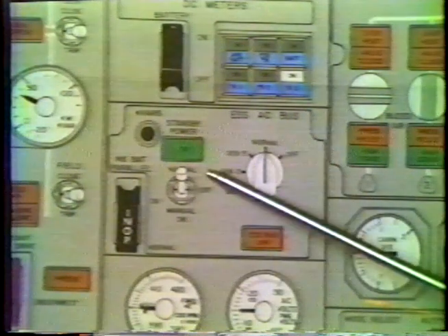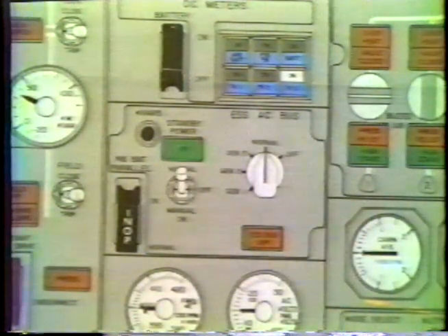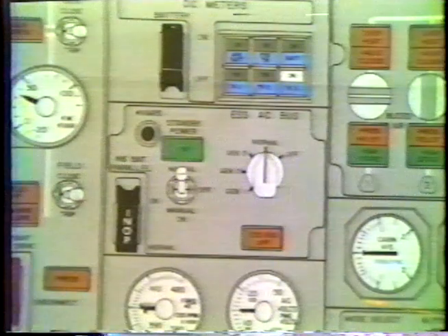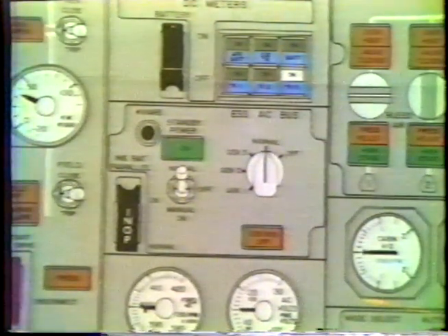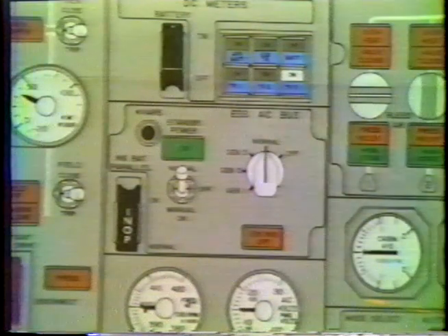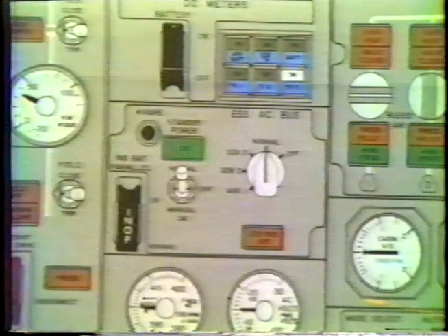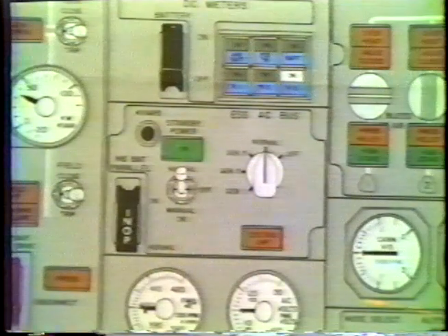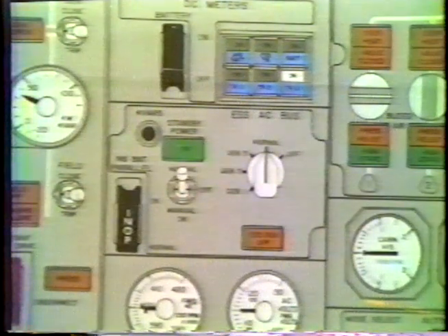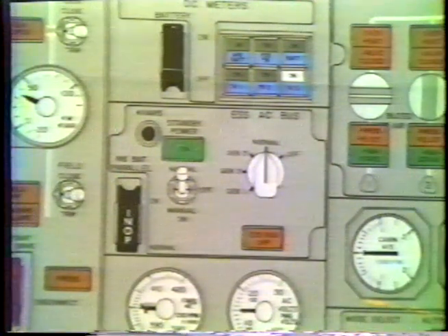With the switch in the normal position, if essential power is available, both AC and DC, the standby buses are powered by the essential buses. However, with the loss of essential power, standby power will automatically switch to the aircraft battery bus and is available to be fed off the aircraft battery or anything that's feeding the aircraft battery bus. And this assures that under just about any electrical condition that could happen to the aircraft, the standby AC and the standby DC buses are available.